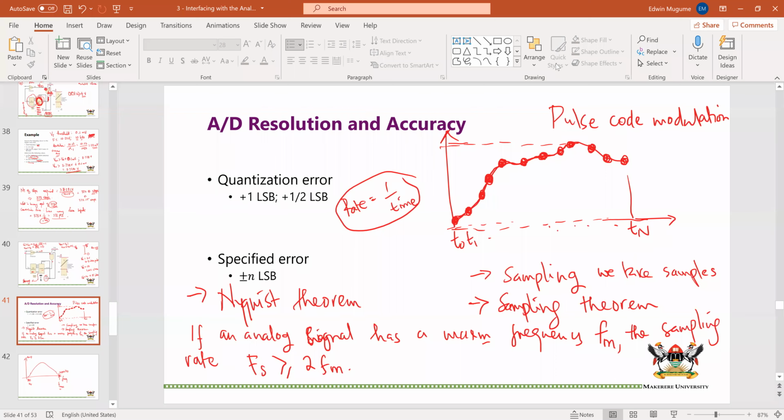Yes. So Gilbert has put it in the chart: a periodic signal, even if it's not a periodic signal, even if it's any random signal, it must be sampled at more than twice. In fact, it is at least twice. You see that the language is important, at least twice. So if you sample at exactly twice, that's okay, but make sure that it is at least twice or more. If it is less, we are going to have a problem,